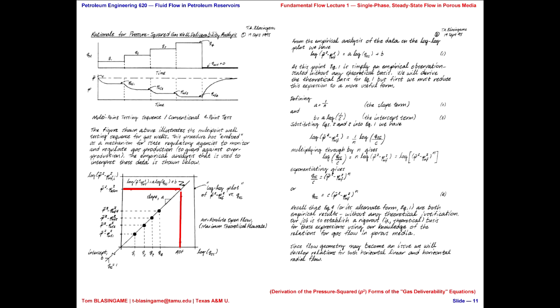So along with income tax, yielding reserves analysis, early reservoir engineering, along with pressure squared analysis leading to absolute open flow, the government comes along and says you must every year report your well's maximum deliverability, absolute open flow in Texas. Every gas well in Texas has an absolute open flow test once a year. Now, it took 4 points to define that line.